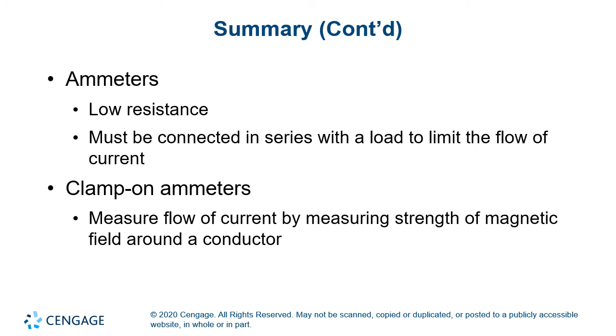That's your standard ammeter. On the other hand, if it's a clamp-on meter, right, one that has a closed loop, it actually measures the current flow by changes in the magnetic field, right? That's that Hall effect. You do have to, of course, close the loop because you need to have a conductor that goes around to measure the strength of that magnetic field.